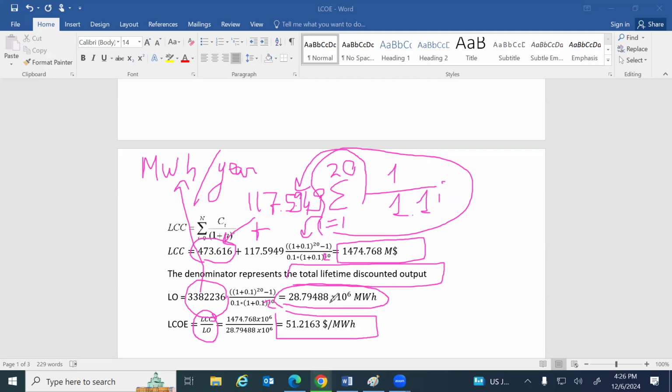Even when we talk about, let's say, a nuclear power plant or a power plant relying on fossil fuels, the capacity factor is high, but you should consider, of course, the efficiency of the thermal cycle, which is of course below 90%. If it's 40 or 50%, it's very good. But then you are talking about conversion from thermal to electrical power. It's different. The capacity factor is related to whether I can operate continuously or not, whether I can supply the needs 24/24 or not. This is the difference. Okay?